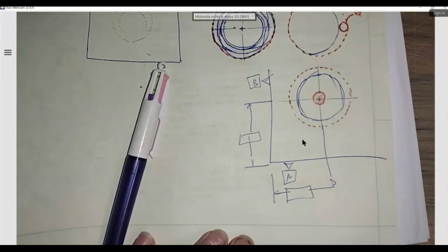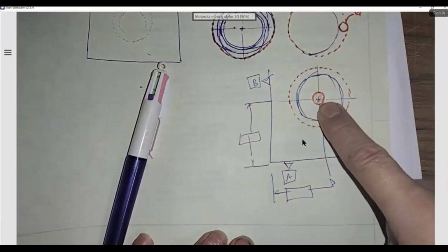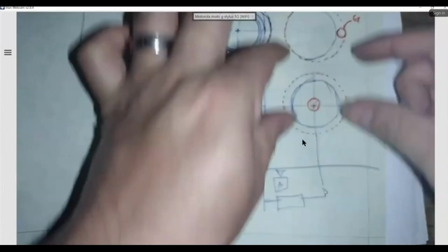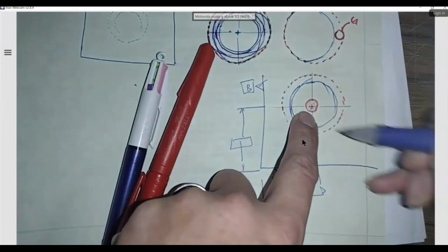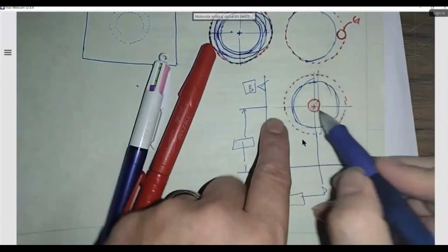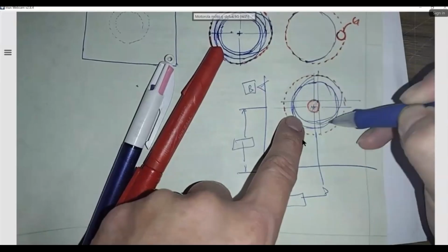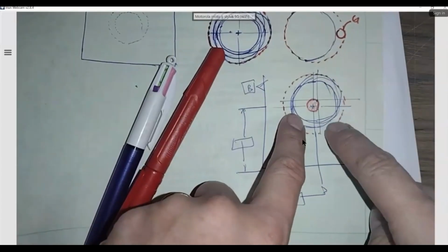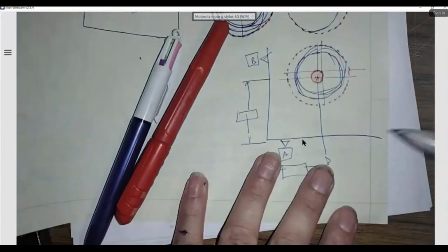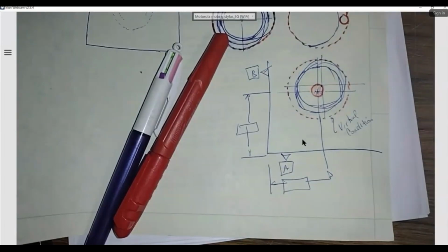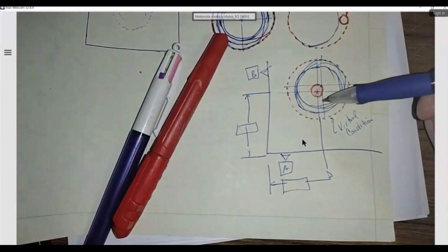In a worst case condition, it will be at MMC, the biggest I can get. And I'm giving it this amount of G, geometric tolerance, so it's able to move to the left, to the right, up and down. And the axis shouldn't get out. If I move it to the left, let's say on this corner, that means my hole will be somewhere there. But it still will be within my boundary. This boundary, we call it the virtual condition. The combined effect of size and geometric imperfection that allows for things to mate all the time.